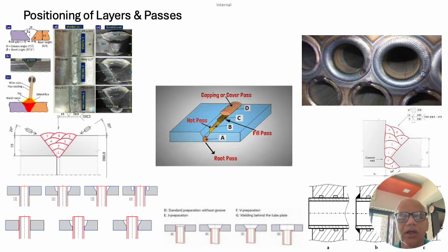If the dilution is going to be less than 10%, it will not create much of an impact, but if the dilution levels are higher, then it will have an impact on every layer, and that is where we need to ensure that we position these layers very well from the metallurgical point of view and also from the non-destructive testing point of view, because based on this positioning of these layers we will be having the resultant gap, and we will be seeing that in our next slide.